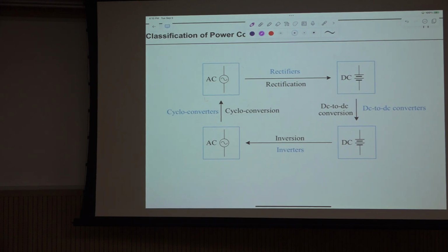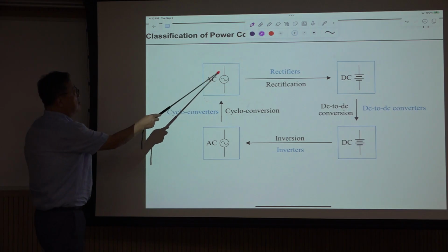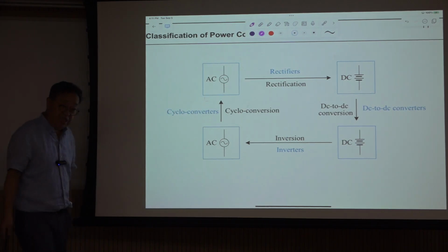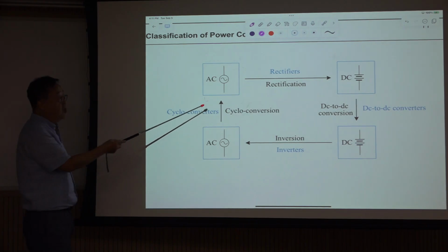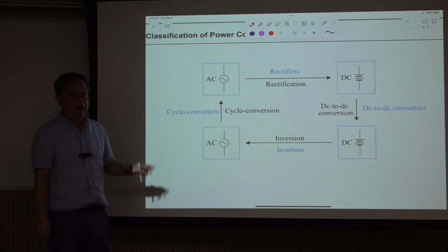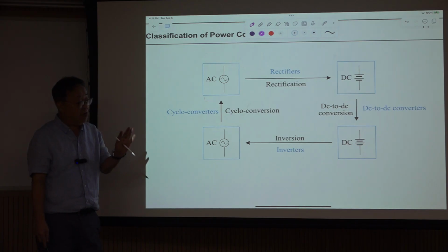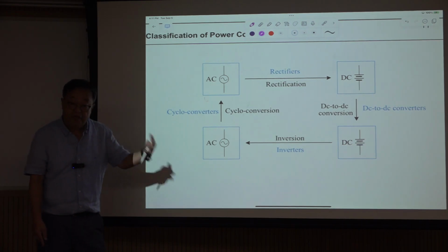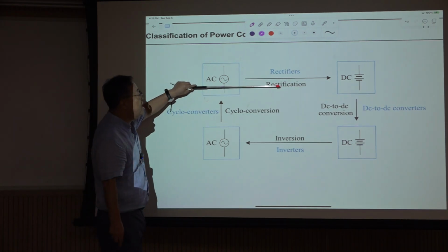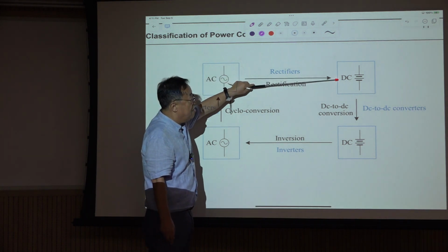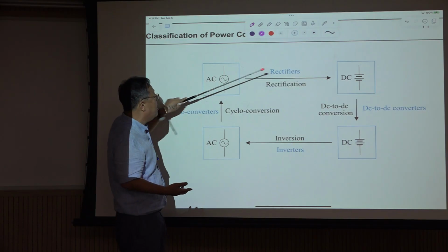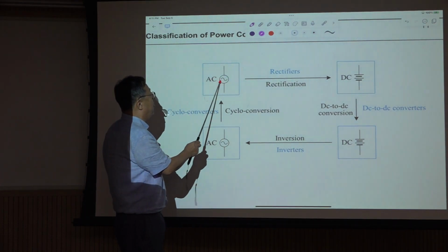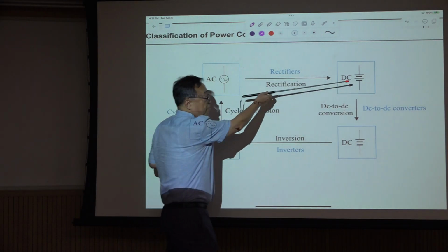This shows some different types of power conversion. Basically you have AC and DC. Sometimes we need DC from an AC source. Then we use a rectifier: a simple diode rectifier, and sometimes a power factor corrected rectifier, but they are rectifiers. We rectify AC and convert it into DC. In terms of the frequency domain, there is some frequency here, but the frequency becomes 0.